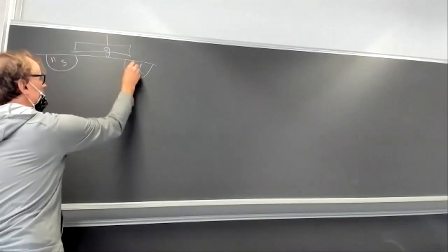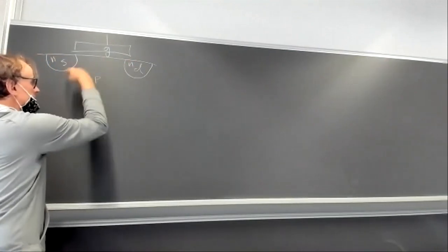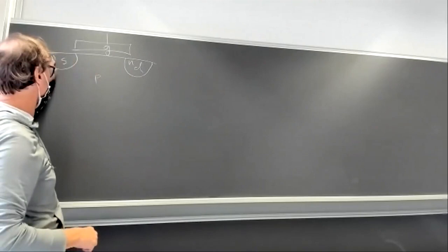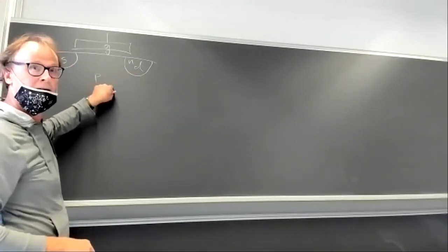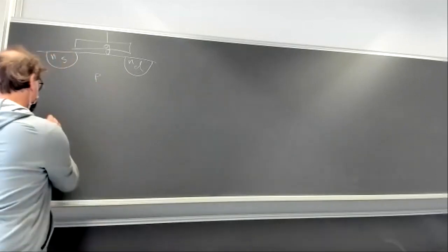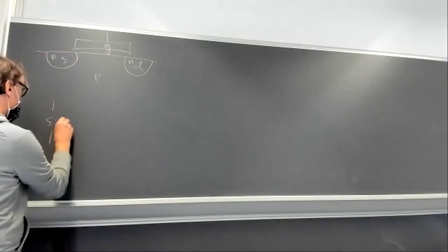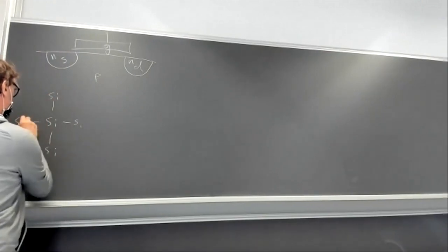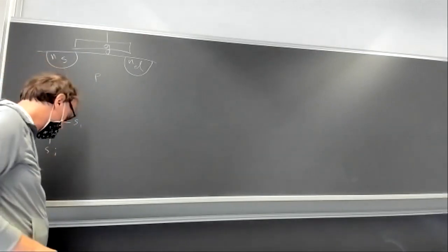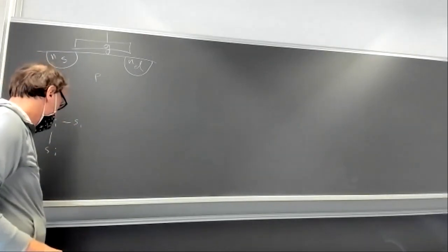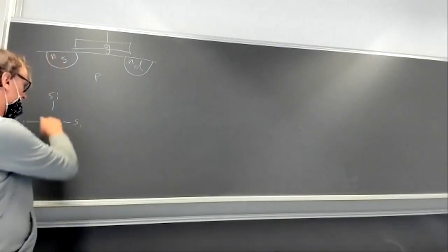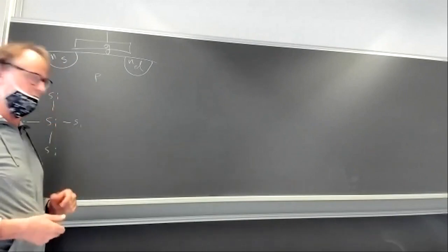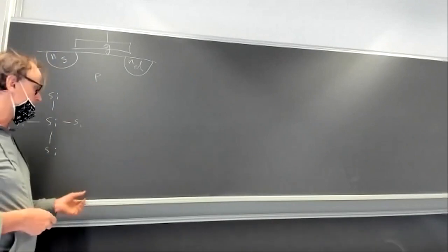So it's doped with electron-rich stuff here, and then the substrate or the bulk of the transistor is p-doped. So it's rich with holes. So lots of electrons whizzing around here, lots of holes whizzing around here. That's because you take the silicon atom, and it's joined mostly to other silicon atoms in this crystal lattice through the 4 outermost electrons. And the silicon atom will give up its outermost electrons here with about 1 electron volt worth of energy. It takes about 1 electron volt worth of energy to break one of these electrons free, normally.